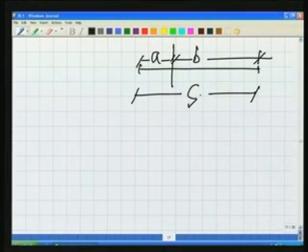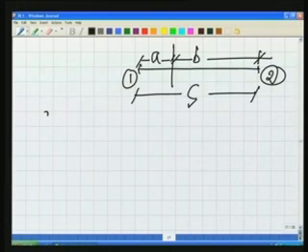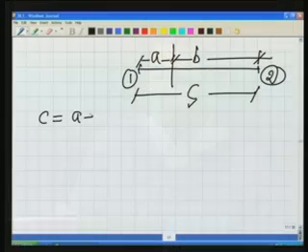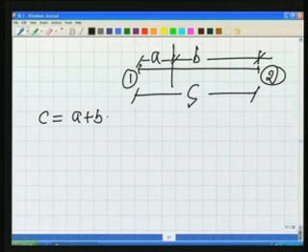So this is a very common problem, and whenever we are doing any kind of computation, we should know how to do this. For our formulation for this tilt of tower, we should know how to arrive at the standard deviation of the final value. We should be able to compute that. Well, a little example here. We want to measure C. We want to determine the length between point 1 and point 2, which we did by measuring A and B. So the length will be straight away written as A plus B. So a length is given to you, but that's not enough.